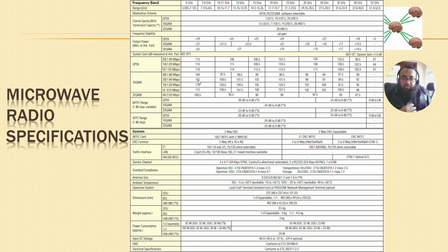For example, to mitigate this, there is MTPC or ATPC. MTPC is manual transmit power control, and ATPC is automatic transmit power control. They are similar, but in ATPC it works automatically, and in MTPC it works manually; you have to change it yourself. But the good thing is one mitigation: for example, if you have a link working on the best QAM, but the weather is becoming bad, the first thing it will do is increase the transmit power with the help of ATPC. How much it may increase, though? Maybe it went to the full transmit power, and still the weather is too bad.